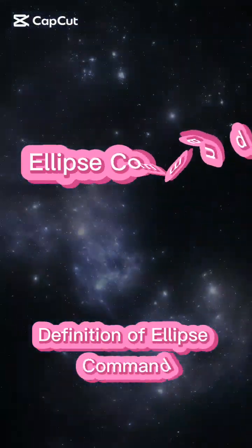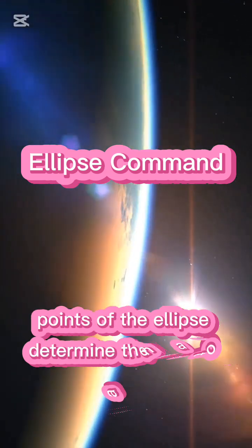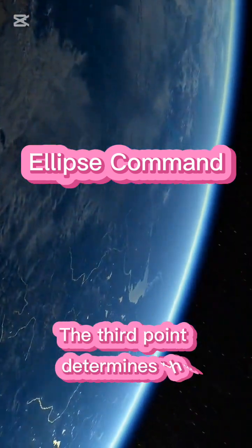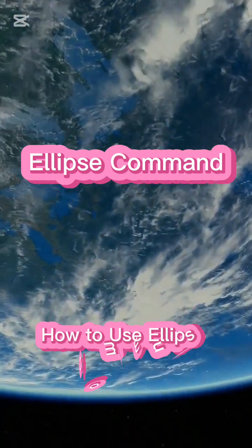Definition of ellipse command. Creates an ellipse or an elliptical arc. Find points of the ellipse. Determine the location and length of the first axis. The third point determines the distance between the center of the ellipse and the end point of the second axis. How to use the ellipse command.